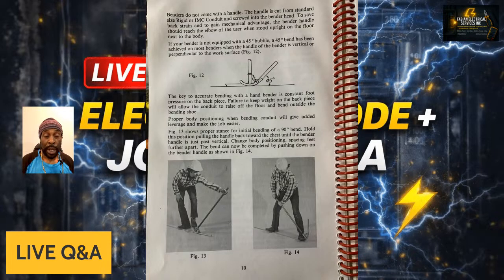Again, the longer the conduit is, the better the pipe will bend. The shorter the conduit is, it becomes very difficult. So let's say you have a 3 feet conduit that you have to bend, or 2 feet. You want to make a stub of 2 feet offset. It becomes very difficult. You can either bend it with your hands, or you can place the conduit on the floor like this and make your bends. So either way, practice makes perfect.